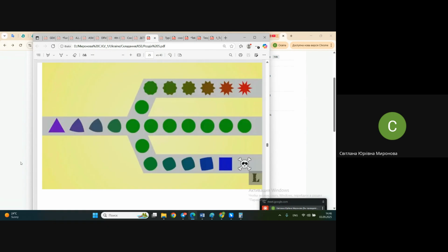Next, if we're talking about creating mockups: theoretical loft, design loft, control print, templates, and out of templates we construct a mockup. How we construct it is another story. Mockup, and next from mockup we start making other mockups. If we're talking about assembly jig, it's called counter standard. Counter standard, mounting standard, assembly jig from this mounting standard, and so on. If we're talking about tooling, mockup and counter mockup of the tooling.